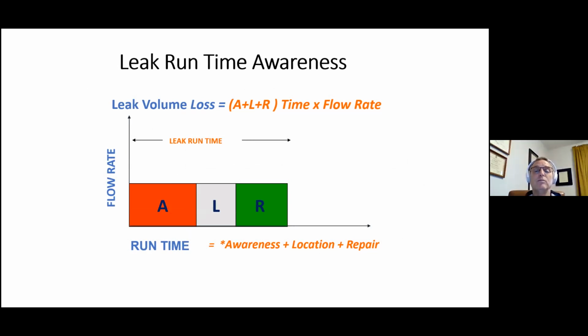That is key for leakage control. But then once you know you have a leak, you must dispatch a crew to actually locate it in the street before you dig it up. So that's the crew you'll often see with the geophone and the nice headphones on their head, and they'll go out and pinpoint it, put an X on the pavement, and hopefully the next day or two a crew will show up and actually repair that leak.